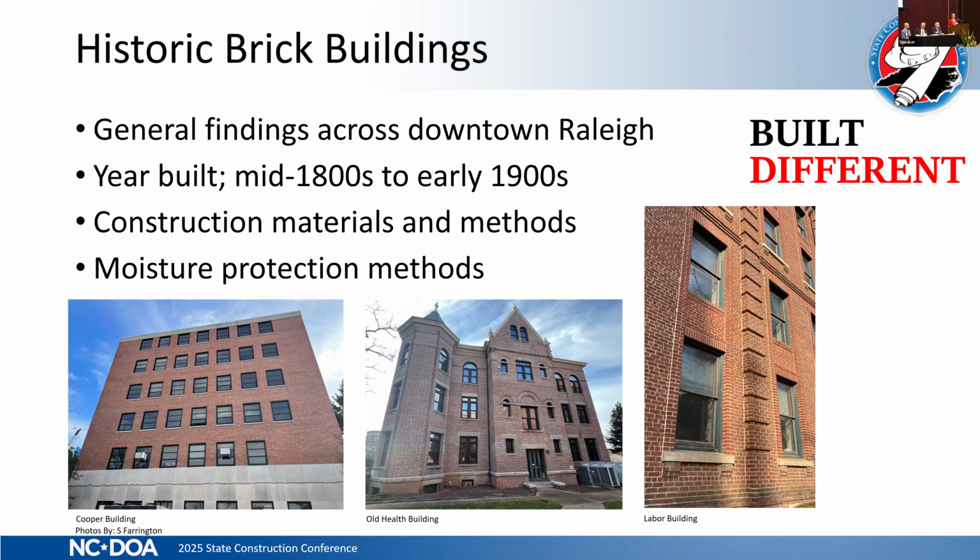The materials that were used for the brick and mortar, again, were meant to allow the moisture to be absorbed and then evaporated before it even got into the building. The mortar was also meant to be flexible, to allow the building to expand and contract, to breathe.